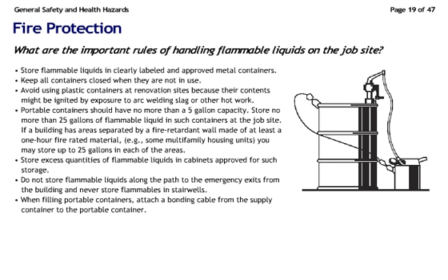Do not store flammable liquids along the path to the emergency exits from the building, and never store flammables in stairwells. When filling portable containers, attach a bonding cable from the supply container to the portable container.